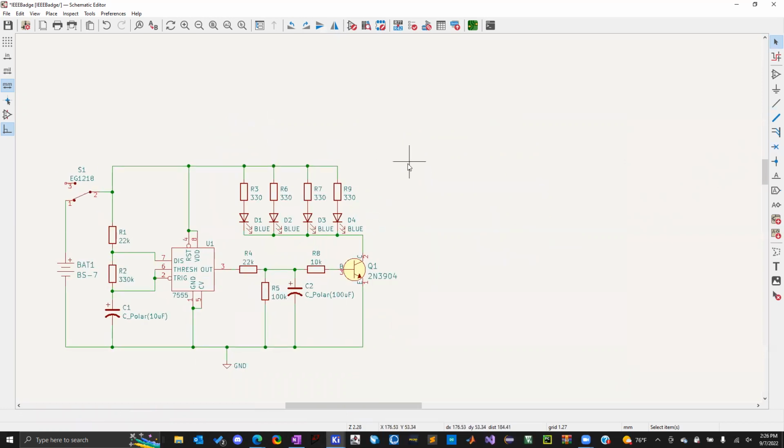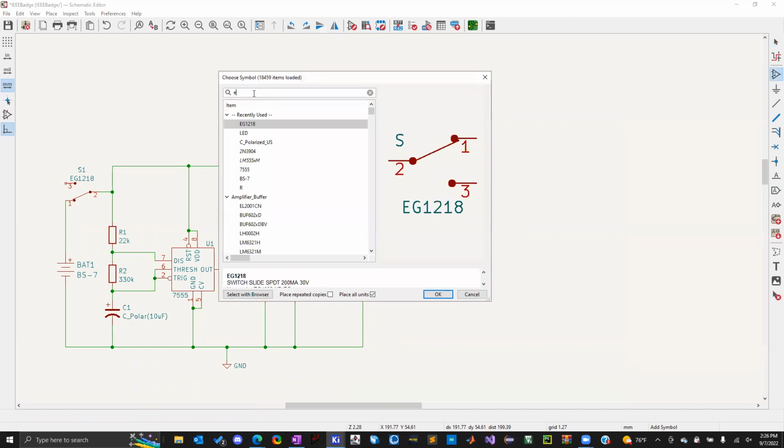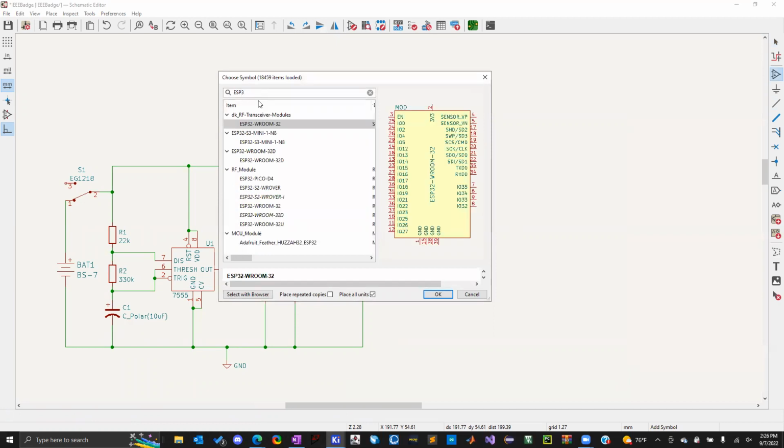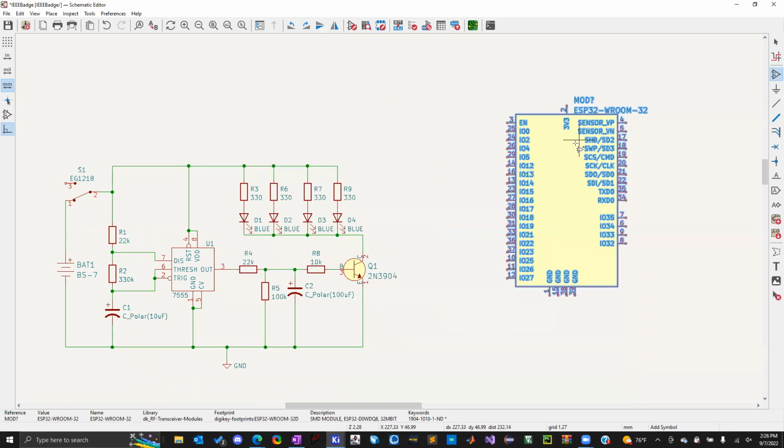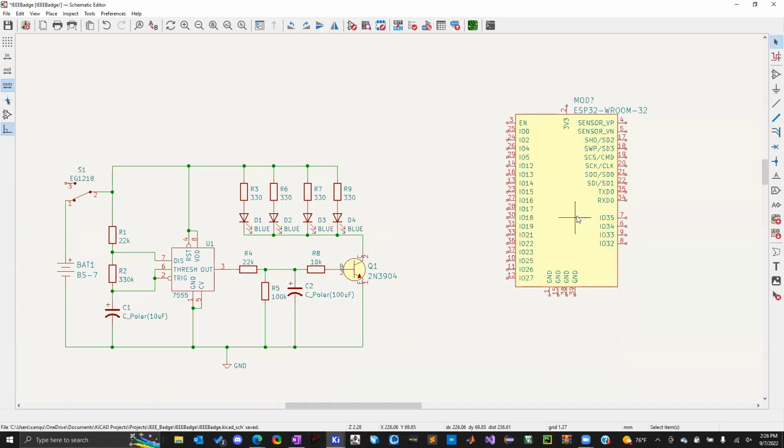Sometimes when you have a really big component, like later on we'll be doing the developer kit, and it has a ton of input output pins. And sometimes you might not want to use every single one of the input output pins. So one of the things you can do is there's this no connect flag, and you can connect that to the pins so that KiCad knows, yeah, this shouldn't connect to anything. So it's a no connect.